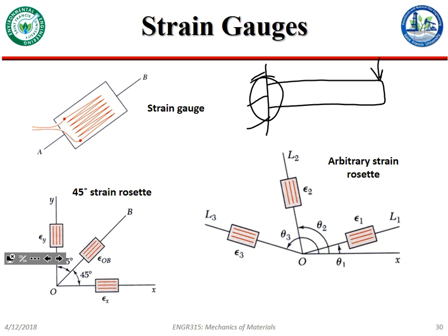But say that, looking down from the end, this is like a wing, so it has a very thin skin panel going the full way around. You can sometimes encounter something called panel buckling, wherein the skin, because it's so thin, will actually fail in compression before this whole thing will break in bending, at maybe an order of magnitude less, so over 10 times less force, which is super intense.